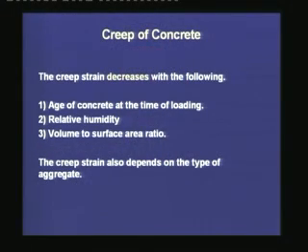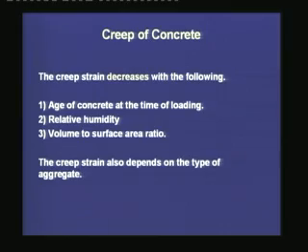And the third is the volume to surface area ratio. If the volume to surface area ratio increases, which means the surface area ratio decreases, there is less loss of moisture and it is found that the creep strain decreases. The creep strain also depends on the type of aggregates. Usually for synthetic aggregates like pelletized fly ash, the creep strain can be higher.